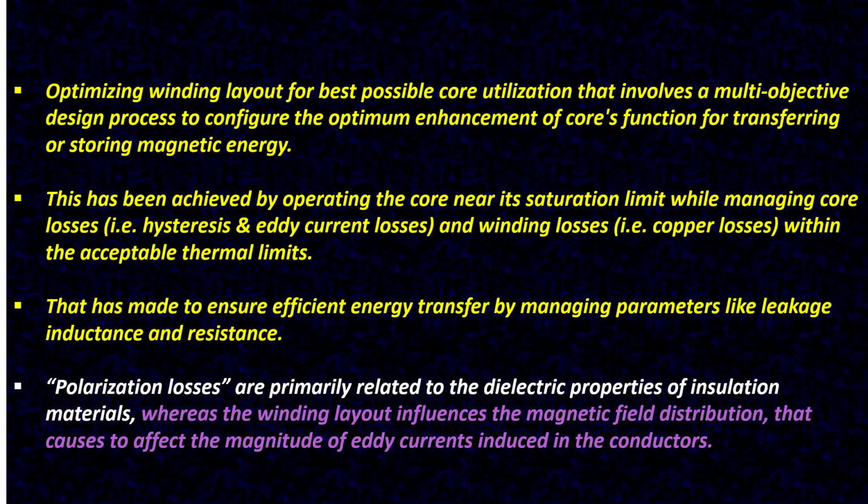This is achieved by operating the core near its saturation limit while managing core losses, that is hysteresis and eddy current losses, and similarly copper losses, within acceptable thermal limits. This ensures efficient energy transfer by managing parameters like leakage inductance and resistance.